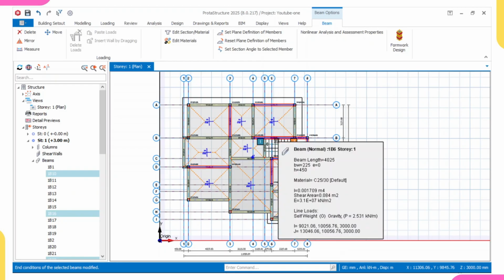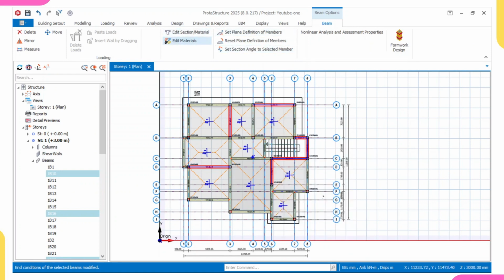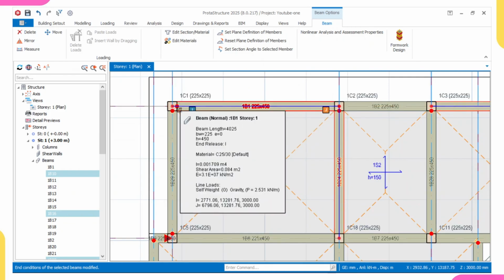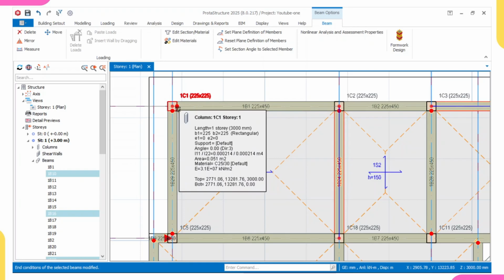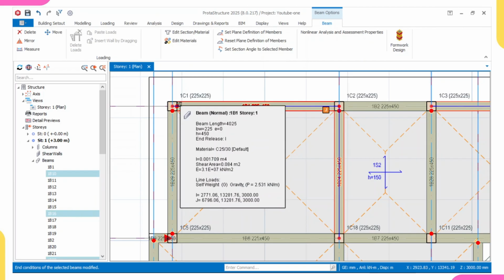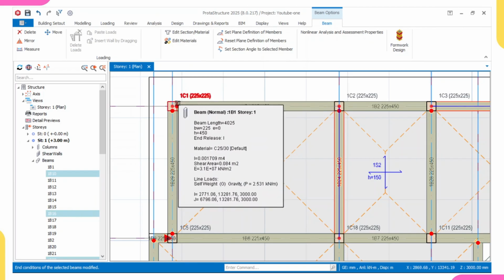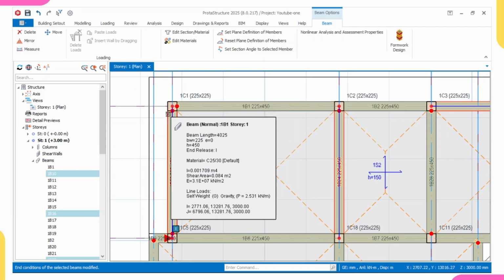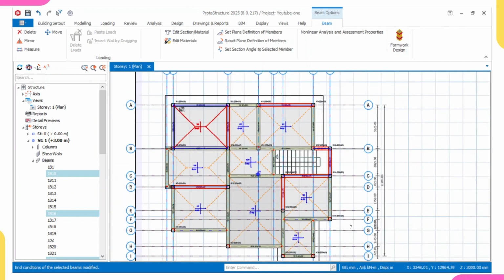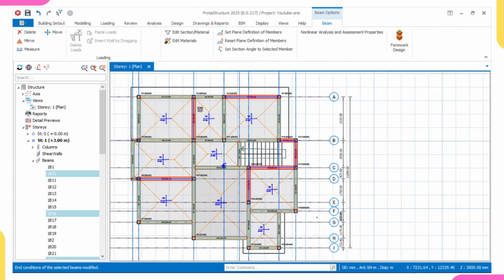So once we're through hinging my beams, remember hinging your beam will help you save cost. If you do not hinge your beam, you'll not be able to save cost. For example, if I do not hinge here, ProtaStructure will be giving me something like 5y16 or 3y20, but since I've hinged here, ProtaStructure will be giving me a normal reinforcement, which is something like 2y16. If you do not hinge it, you are not saving cost, because ProtaStructure will be providing higher reinforcement, since there is a moment at this point, and ProtaStructure must surely design to counter that moment. I don't know whether I've explained this beam hinging for you very well.